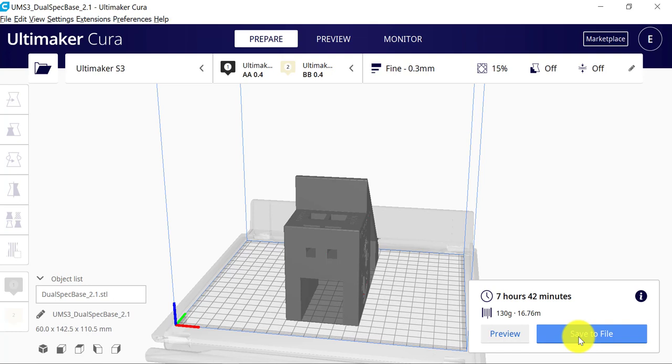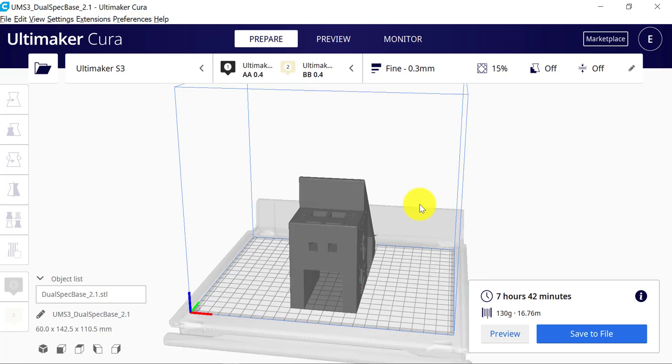You want to make sure at that point, though, you've already added glue and cleaned up the print base, because once you send it over, it's going to automatically start. It's not going to allow you to release the job like a laser cutter will. It's going to just start through the routine. So if you've got something on the build plate, it's going to fail your print.